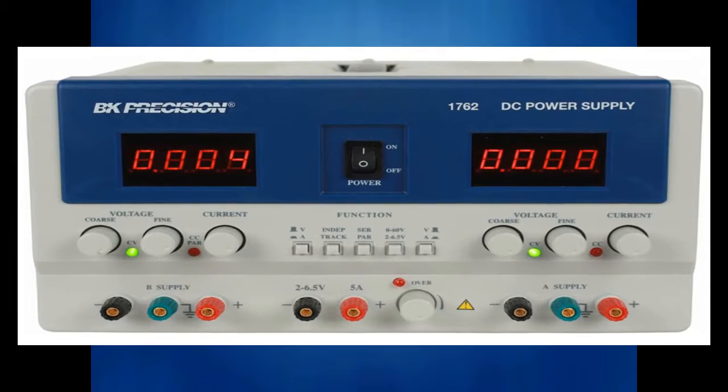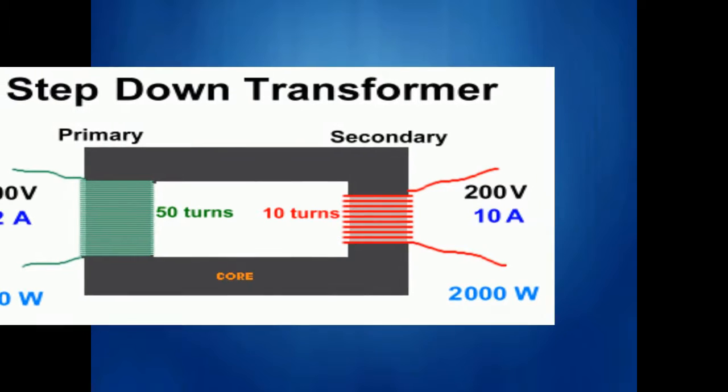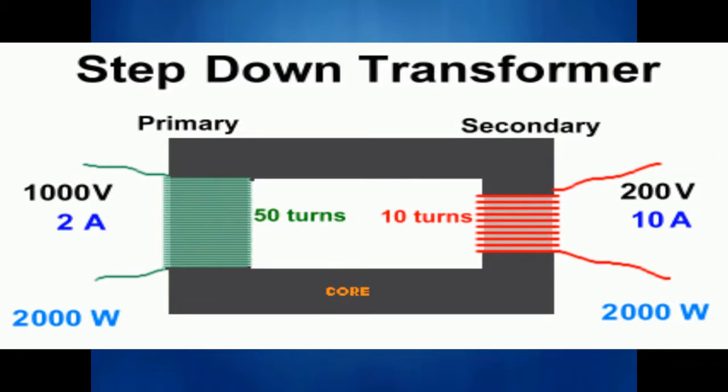So first of all, there is a transformer. The transformer is used to step up or step down, usually step down, the supply voltage as per the need of the solid state electronic devices and circuits to be supplied by the DC power supply. It can also provide isolation from the supply line, an important safety consideration. It may also include internal shielding to prevent unwanted electrical noise and signals on the power line from getting into the power supply and possibly disturbing the load.